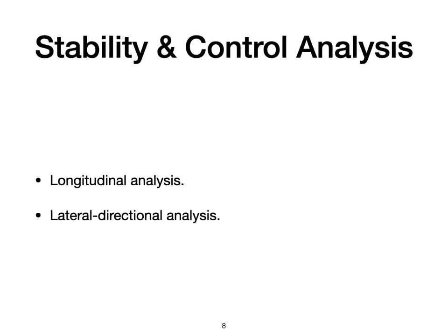Longitudinal static stability and control. Before this concept, in stability and control analysis, most aircraft being symmetrical about the center line, moderate changes in the angle of attack will have little or no influence upon the yaw and roll. This permits the stability and control analysis to be divided into longitudinal and lateral directional analysis. Longitudinal involves only pitch, and lateral directional analysis involves roll and yaw.